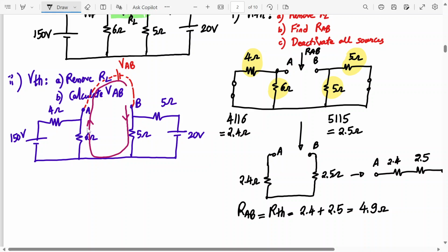These are independent meshes. So here let me draw the current. So current here in this direction. Let me draw the current here in this direction. This is what you were saying, right? Define the currents. Yes. Now you apply the KVL around this internal loop. This I have drawn. This red color supply and this loop. So if you apply KVL there, what do we get? You start from point B, and you go up till you again arrive at B.